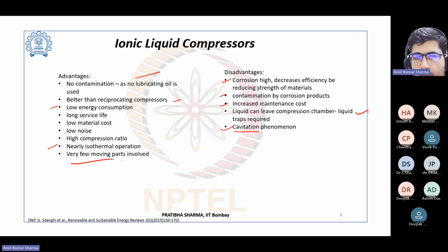So does anybody know about cavitation? Yes, sir. The output pressure goes down below vapor pressure. Then there is a sound, the vapor blast. I'm just telling briefly, that phenomenon is called cavitation. Yeah, nice. We have seen the cavitation phenomenon multiple times in fluid dynamics when dealing with pumps, turbines and all, but it occurs in compression also.